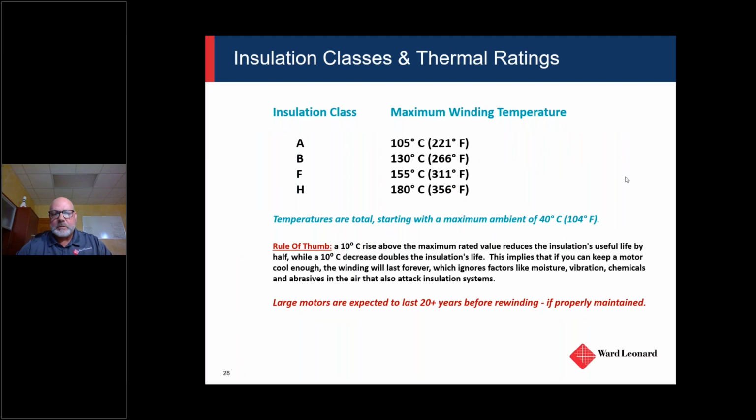And then insulation ratings, this is important because we get into this conversation a lot, especially on specs, when folks are asking us. Especially when we're winding something, what we use are Class H materials in our rewinds, but most of the OEMs are using Class F materials. Okay, and that's the difference. It really is the difference in what winding temperature the motor has the ability to operate at.